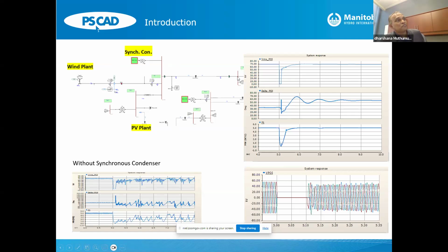A second point is if you had more lines connected to this bus, if the transmission system was stronger with parallel lines coming into this bus, that would also increase the short circuit strength because the impedance would drop. That also helps stability of operation of IBRs, because if you had more lines, tripping one line would not have caused a big jump like this, right?